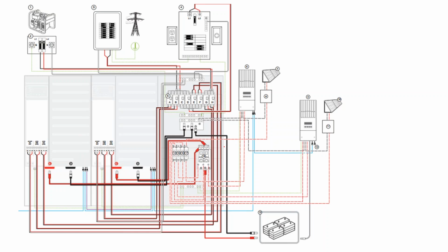The one thing that I would think about is, if you have a positively grounded battery, you may need to have negative breakers as well as positive breakers. That's kind of the extent of my knowledge on that.